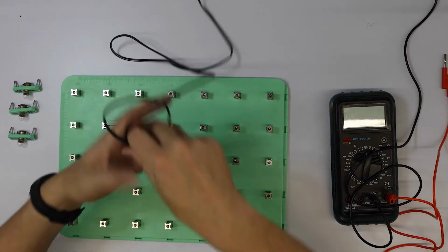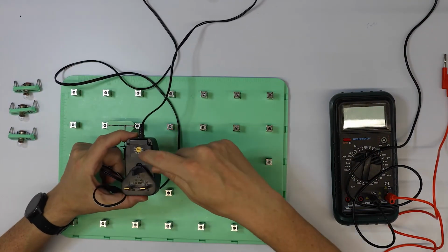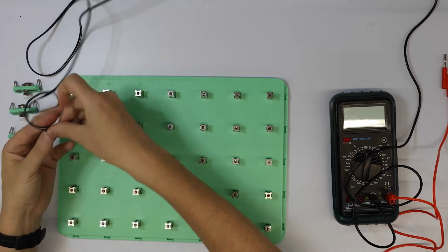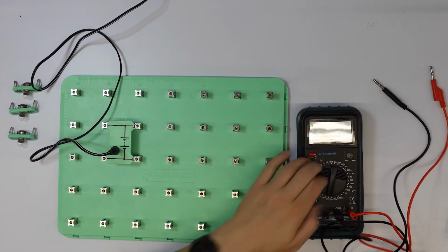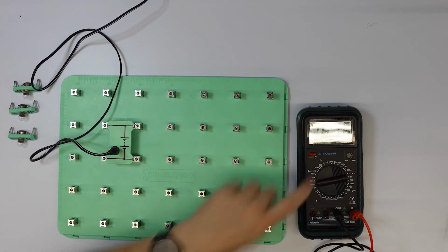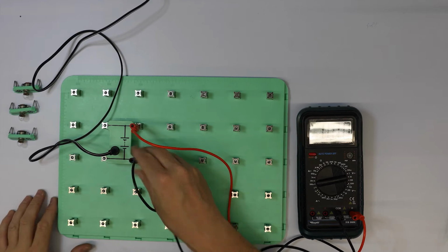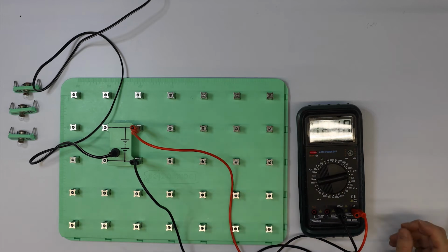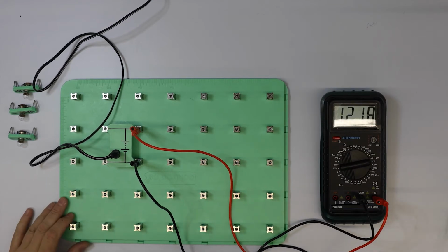So here is the end of my power supply. Just double check, the power supply here is configured by turning this dial. Make sure that's set to 12 volts, so I know that's the case. Plug that in here, and I'm going to connect that to my component here. I do have a multimeter here, remember from the last experiment. So let's just double check that we have 12 volts appearing across this. I'm going to connect once again the red lead to the positive terminal, the black lead to the negative terminal. Oops, on the wrong setting. Connect that there, and sure enough, we have 12 volts across that power supply. So that's good. We know that everything's going to work.